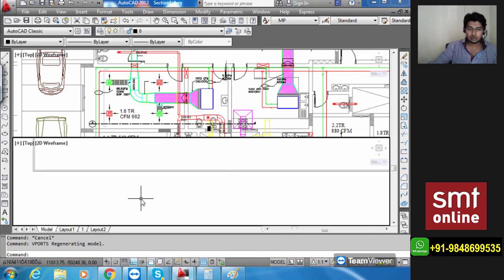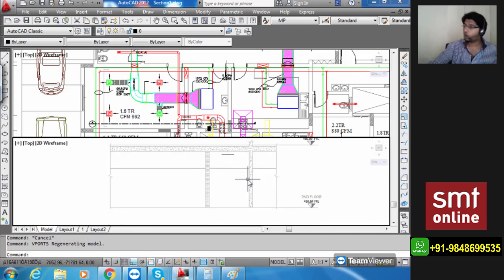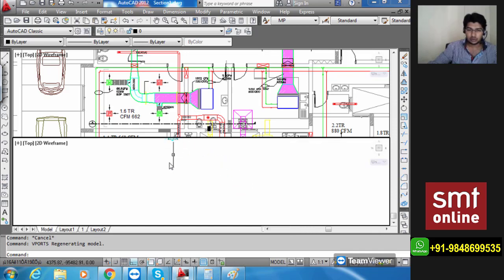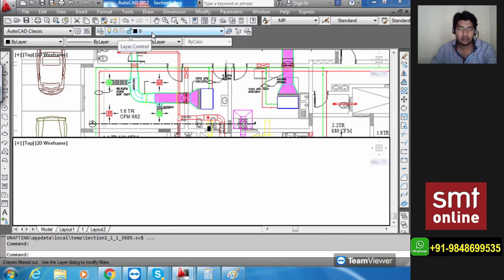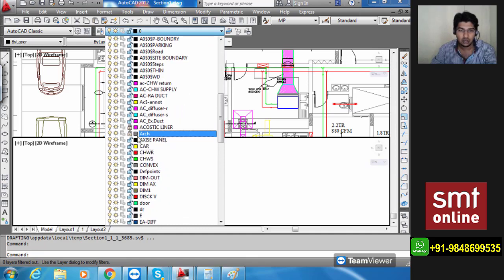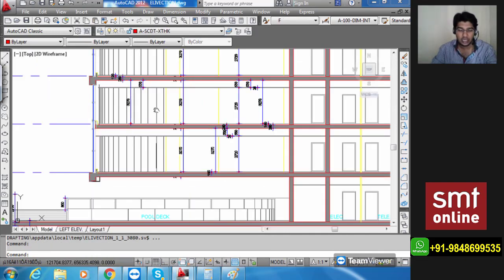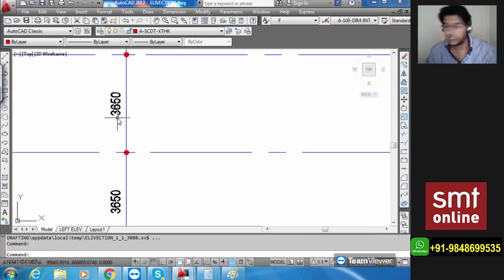And over here what I want to do is create an empty room for me to draw one particular architectural slab of only this much section. So I'm going to come to an empty space inside and zoom that very nicely. Here I'm going to draw one single line. Remember, we have an architectural drawing layout, which is currently locked. I can turn that on and make it the current layer, and you can see that it is available. If I use line and draw one line of any particular length, my offset has to depend upon the actual floor height, that is nearly 12 feet. Alright, it can even increase.